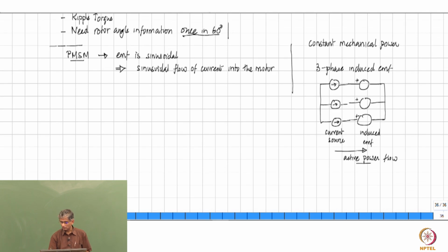How do you find out how much active power flows in this electrical circuit? RMS is one way, but RMS means that you are looking at one cycle of the waveform and then you take an RMS of that. RMS does not say how the waveform is going to be with respect to time, right? RMS is a sort of lumped information about the entire thing, leaving out the details of what's happening.